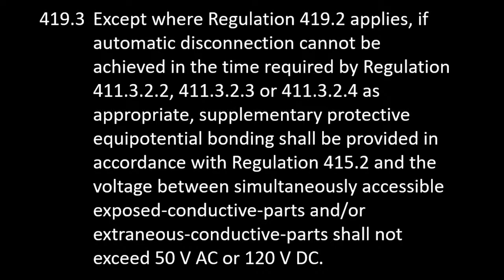All have their pluses and minuses. I suppose what you've got to consider is the amount of metallic parts available at the origin to which you can bond. So you're looking at metallic structure, which will help to bring that Z value down to meet the disconnection time. But yeah, numerous options.